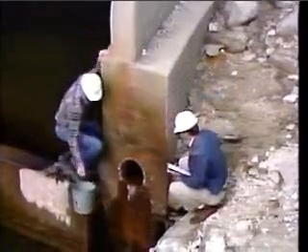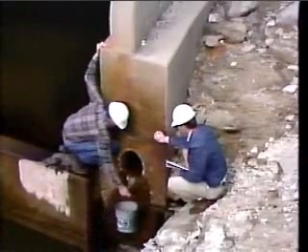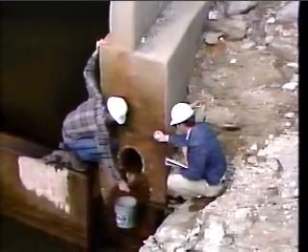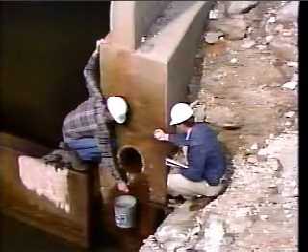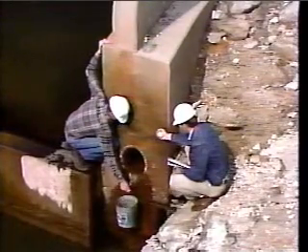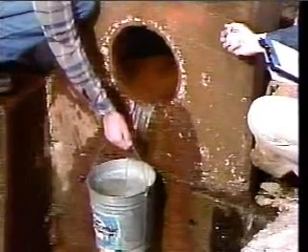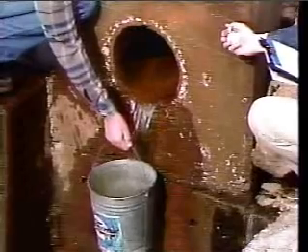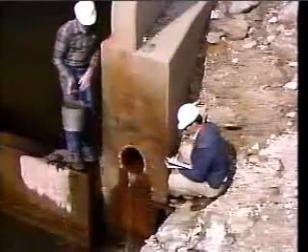Now, let's talk a bit about the correct way of measuring the flow rate. If the flow rate's not too great and the seepage is accessible, such as seepage exiting from a toe drain pipe, use a bucket and stopwatch. You can also install a weir for measuring rate of flow.